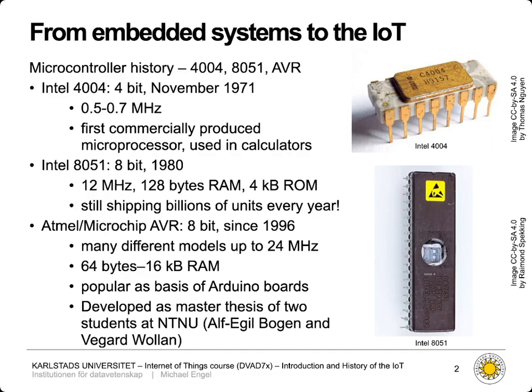So it includes much more functionality. In addition to the RAM and ROM and the microprocessor itself, the 8051 had some improvements in terms of peripherals. You could also communicate with external devices directly without requiring additional ICs. What this means is you could build single chip solutions for embedded systems. This 8051 chip was all you needed.